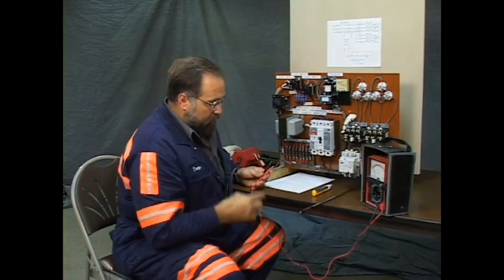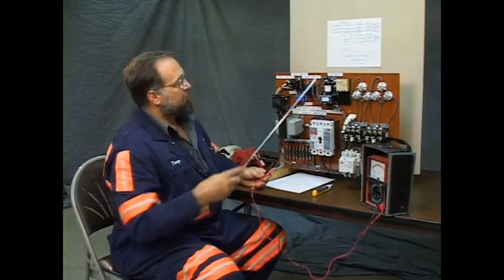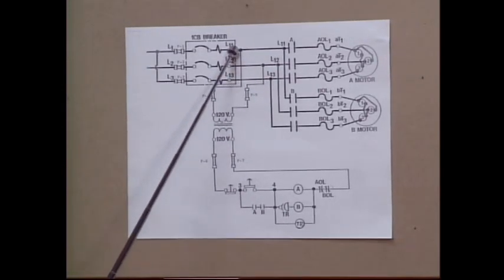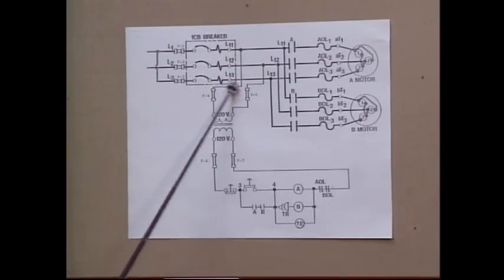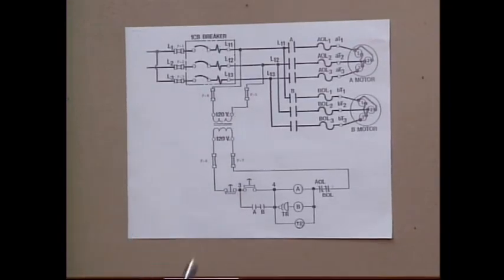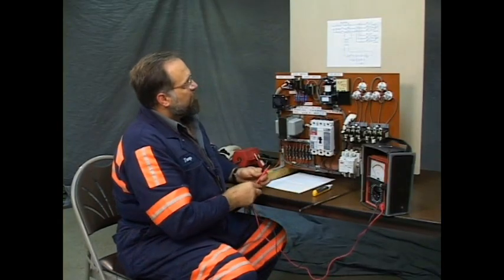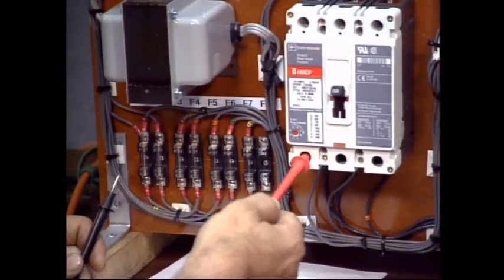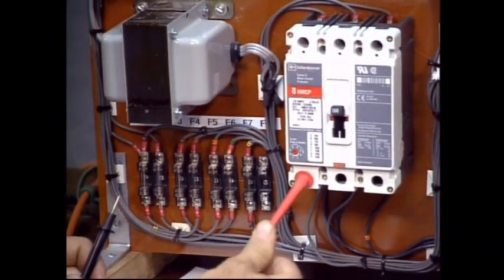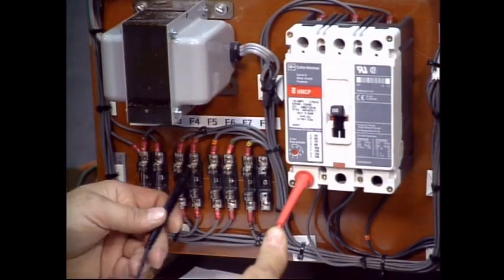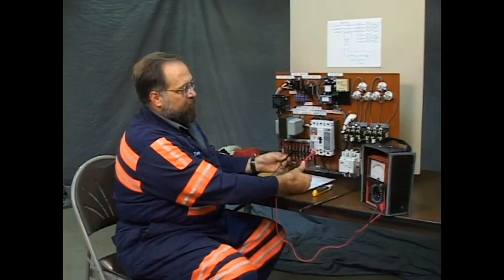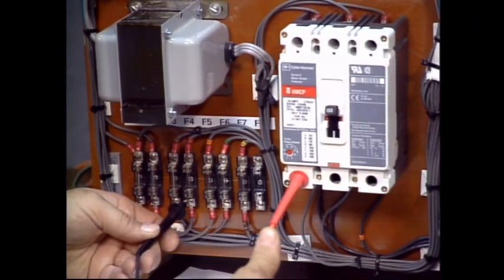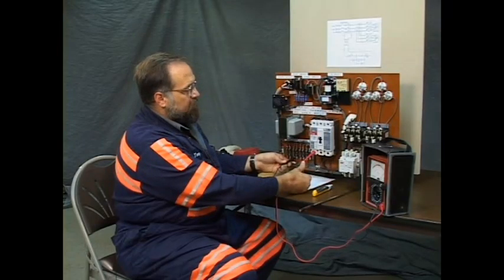The control is the portion of the print that's not operating. This circuit, the control circuit, originates at the load side of 1CB. So I'm going to start our testing there. Let's begin at L11, the load side of 1CB. There's a wire that goes to the line side of F4. If you can see, there's no resistance. That's good. Let's read through F4. And again, it's good.